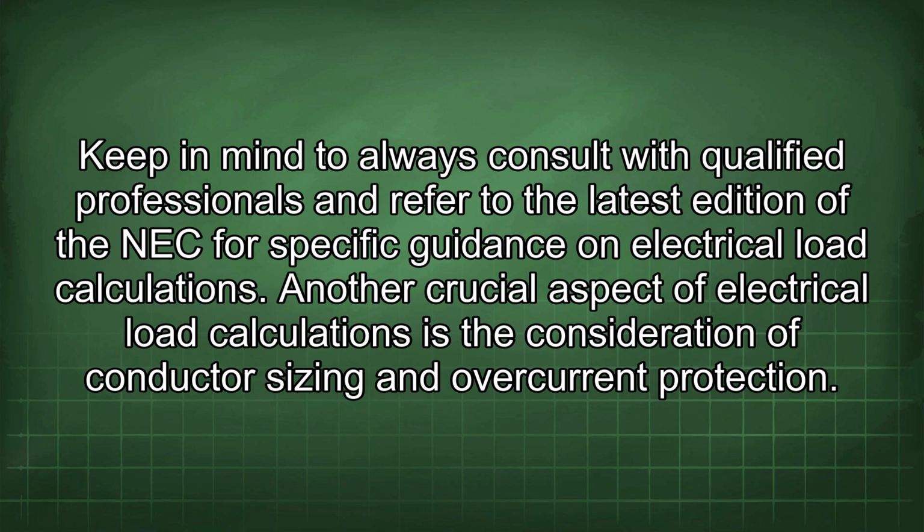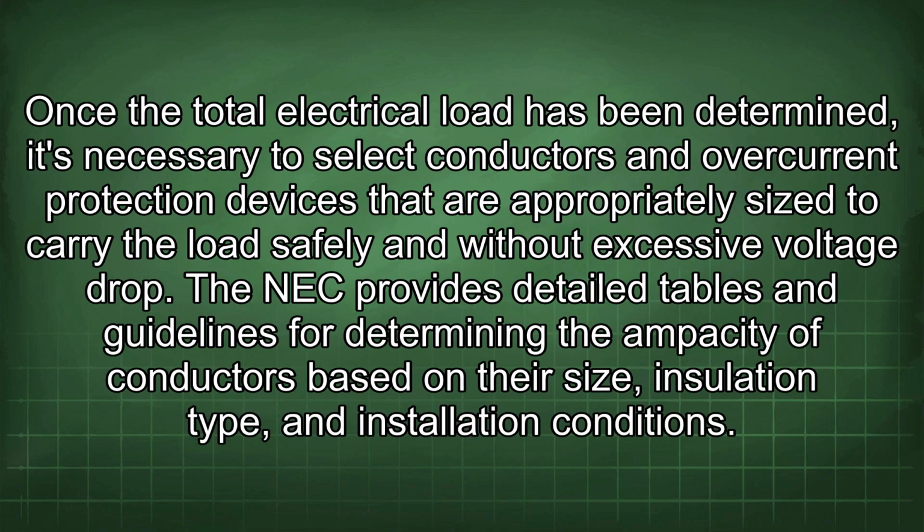Another crucial aspect of electrical load calculations is the consideration of conductor sizing and overcurrent protection. Once the total electrical load has been determined, it's necessary to select conductors and overcurrent protection devices that are appropriately sized to carry the load safely and without excessive voltage drop. The NEC provides detailed tables and guidelines for determining the ampacity of conductors based on their size, insulation type, and installation conditions.